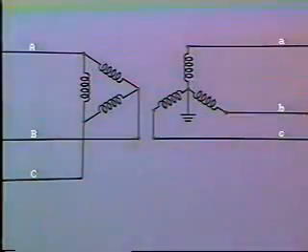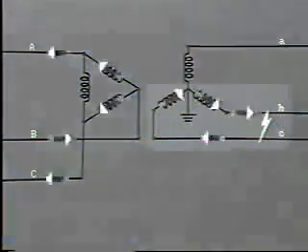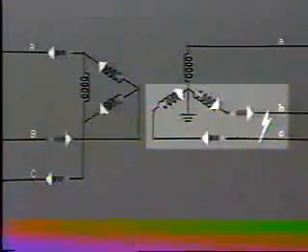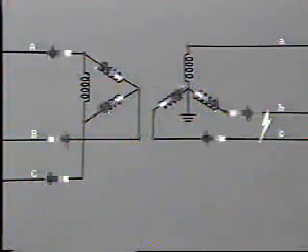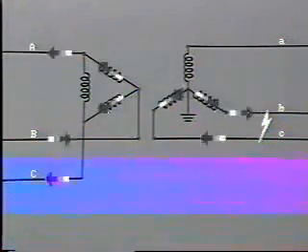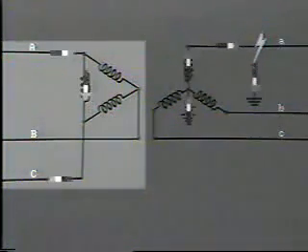In the case of a phase-to-phase fault on the secondary, in this example between lines B and C, then heavy fault current will circulate in the secondary B and C phase windings, and likewise, heavy current will flow through the associated windings on the primary. And this will be in addition to phase A load current, which is still being supplied. Where there is a ground fault, in this case on line A, additional current must flow through the associated phase on the primary, like this.